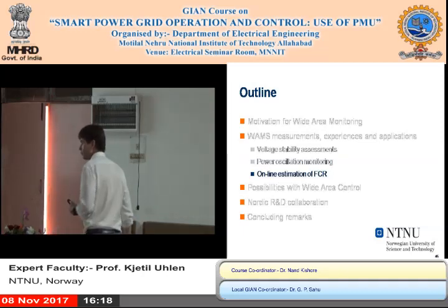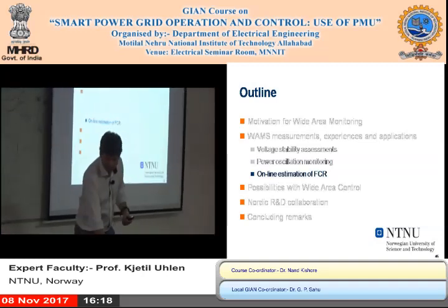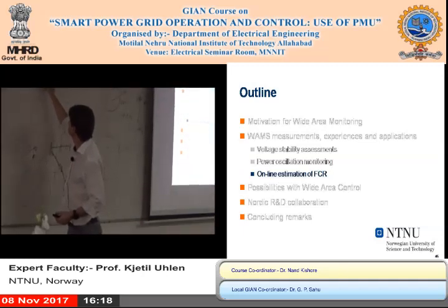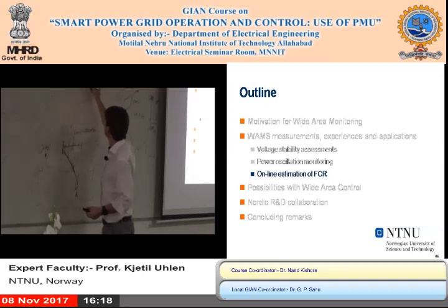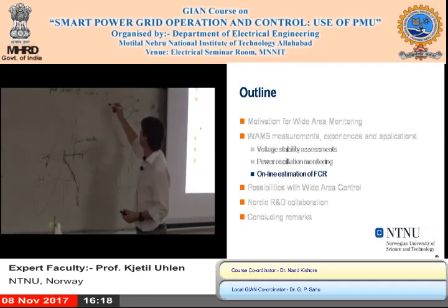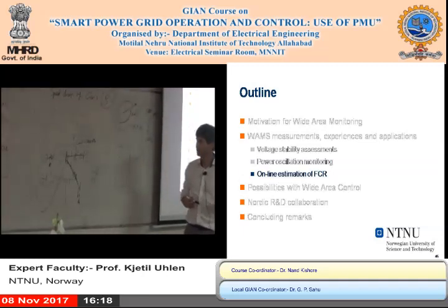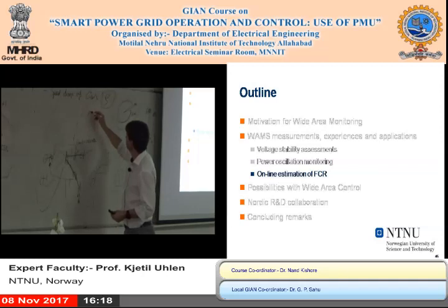In other words, we want to estimate things like the speed governor of generators, the rho parameters we talked about yesterday, because that is a measure of the provision of reserves from that generator. You can turn that into megawatt per hertz.